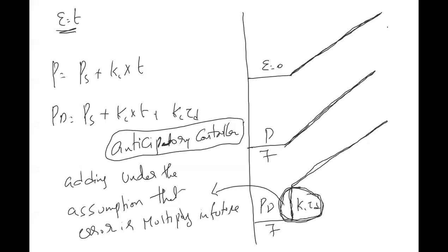It's because it is a ramp input of error. For some reason, error is continuously increasing. So that is why this extra addition is good. But what is the negative point here? Now my error is 0. Say error deviated slightly, not because there is a disturbance, but let's say a small error of 0.1, or let's say 0.2. 0.2 is a very small error.